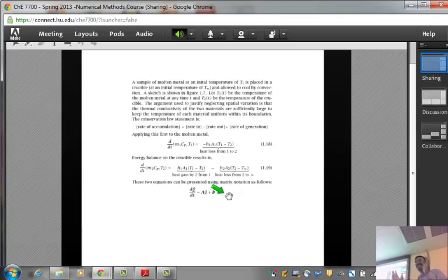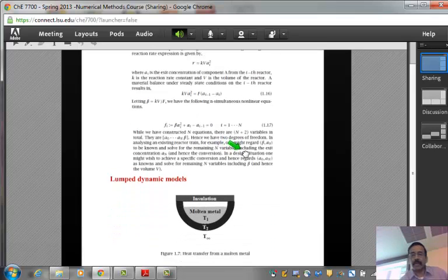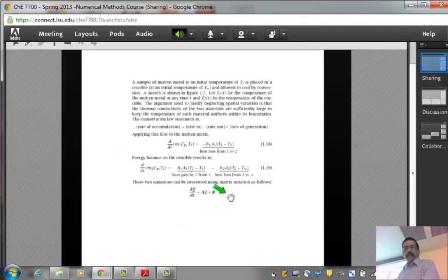No? That's good. So you write an energy balance equation this time, one for your control volume with only the molten metal as your control volume. The second energy balance equation you write with only the crucible as your control volume. So identify what flux of energy is there from one control volume to the other control volume, and you can get the equation for example, rate of change d/dt of m1 c1 T1. That is the energy content in the molten metal.